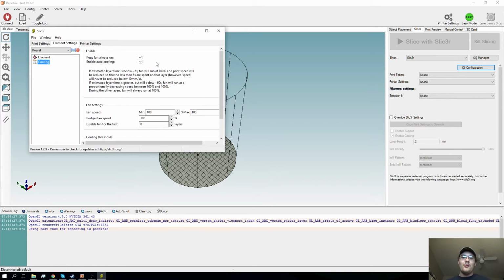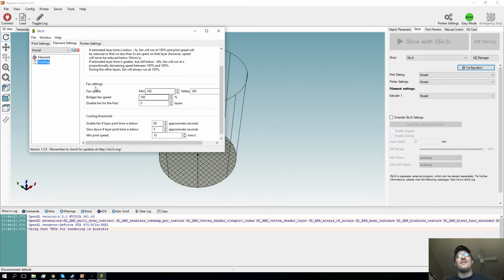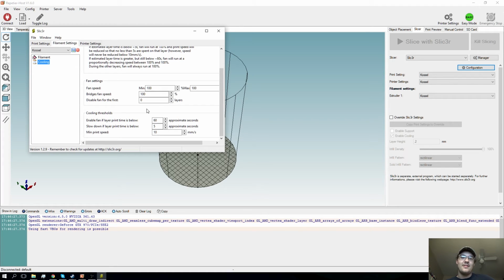If you let the middle tube of this extruder specifically get too hot, then it's going to clog up everything, and you don't want to do that. That's not good. So just always have the fan on in here. And then a couple other things, there's this fan settings. If you want to install another fan that only does the print and you have this one just blow on the extruder itself, then you can set all that up, and this is where you can adjust stuff like that.